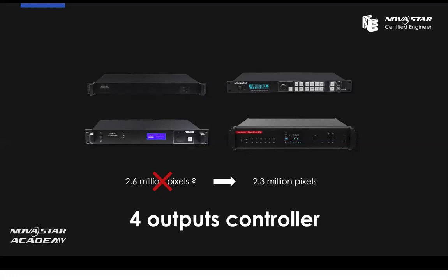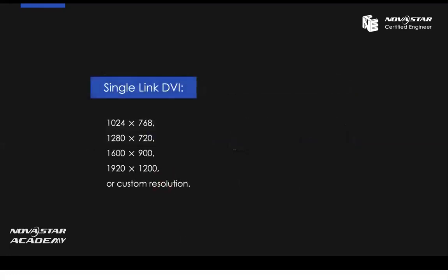Why can't I get the full loading capacity? Now I will give you the reason. All of our 4-output controllers use single link DVI as input. These are the normal single link DVI resolutions. We see the maximum resolution of single link DVI is 1920 by 1200.